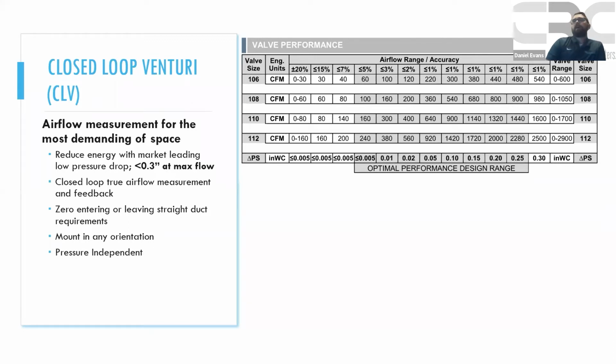Pressure independence. It is a pressure independent air valve. Why is pressure independence important? Well, one of the biggest things is, when we get into these spaces, we're trying to control airflow and manage airflow. So one of the large areas that we have is how do we ensure that this envelope or this space that we're working on can stay repeatable and reliable and detach us from what might be happening in the system? We may have some things that will cause a system to change its effective static pressure. We don't want that to affect the amount of flow or volume we can move through the spaces. So the CLV is pressure independent.